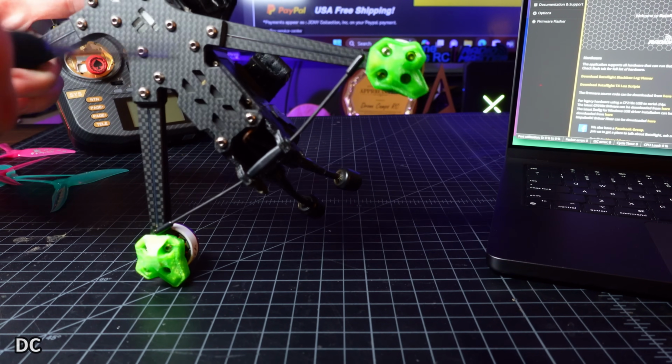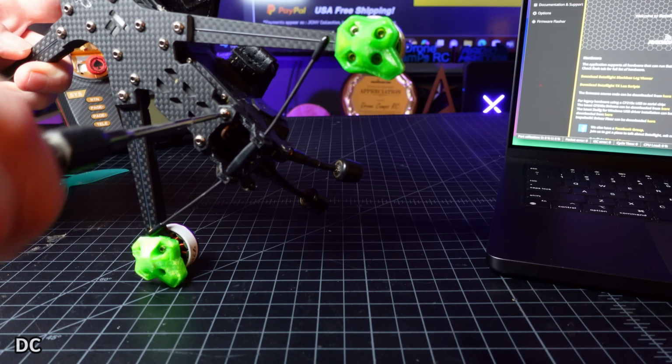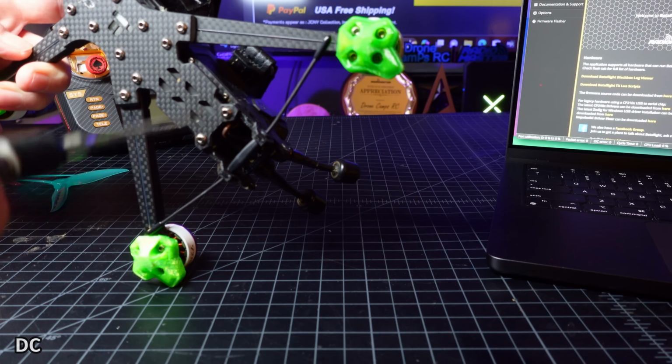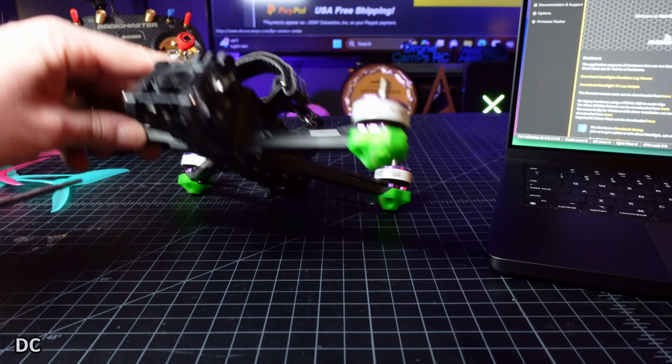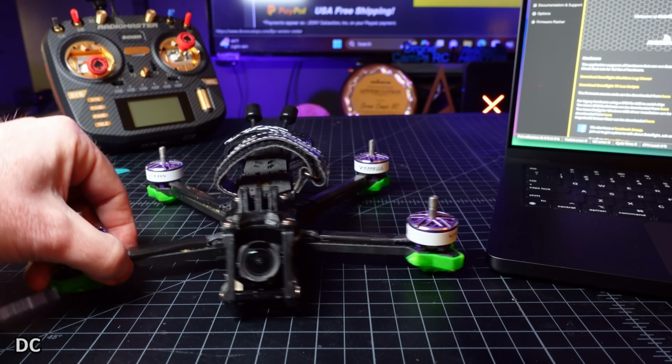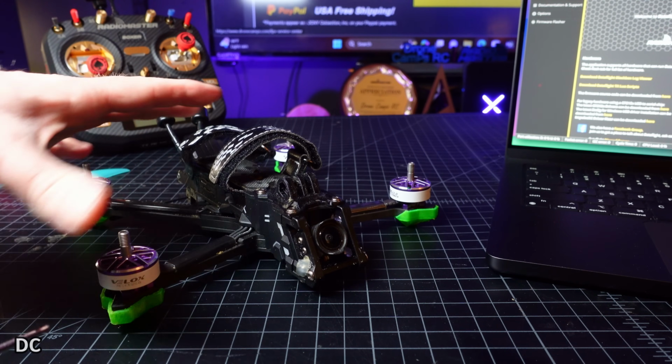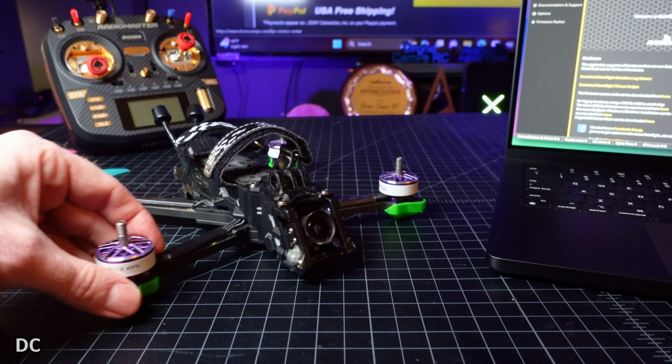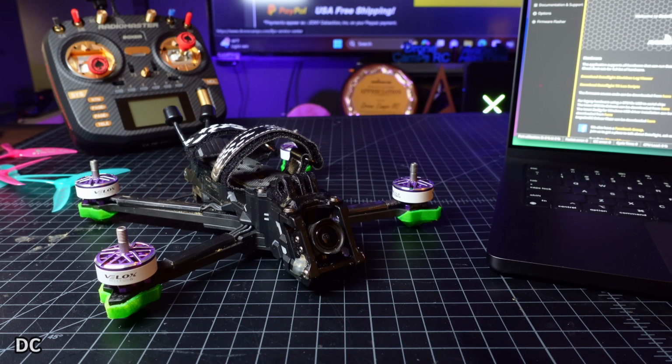It's a good idea to go over your quad, I'd say every 5 flights or so: frame bolts, motor bolts, top and bottom plates, as well as all the arms. Make sure that all the bolts are nice and snug, because over time they can loosen up, and if a motor flies off, that will definitely cause a crash. So you always want to have nice and tight hardware on your quad.